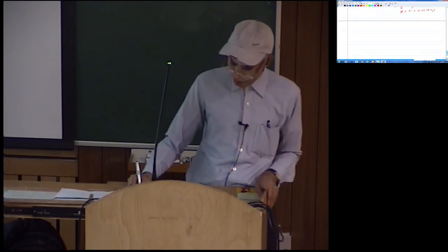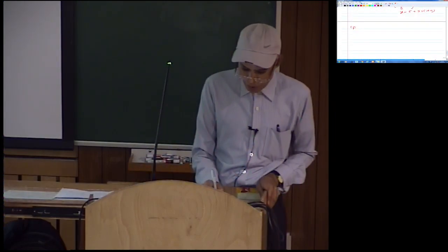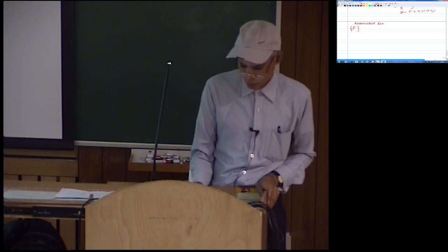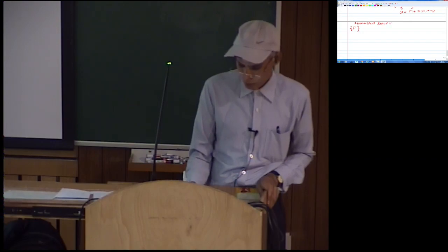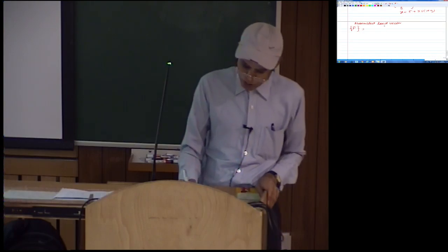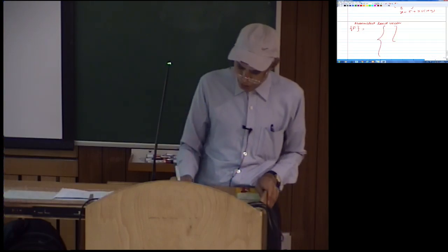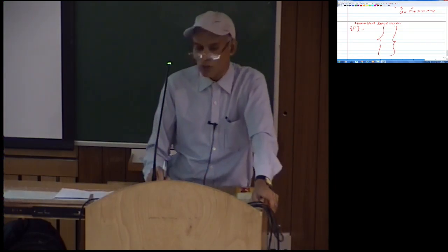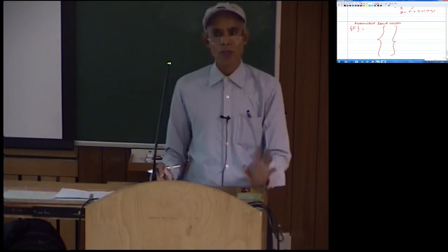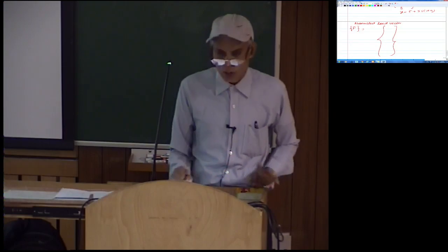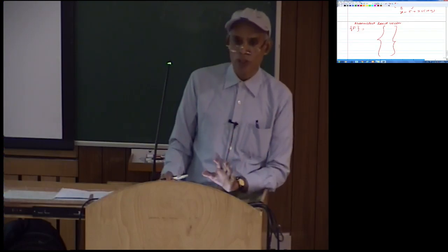So if you look at finally the assembled load vector F, this will have how many elements in it? What would be the size? Because there are total how many nodes? 6, and at each node we have 2 degrees of freedom, so it's going to have 12 entries. Now the sequence would be in terms of global node numbers.